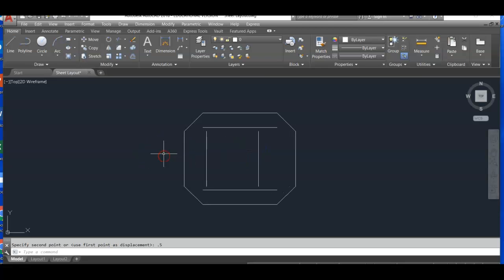0.5. Okay. Now we've got to clip these corners off, but take note, these corners aren't snapped together. That's one thing that's nice about this chamfer tool, it doesn't have to be. So we're going to go back to our same settings, except here the distance is not 1/4 inch, it's 1/8 inch. So I'm going to type 0.125, hit enter. The angle is the same, 45, so I'll hit enter again. Watch this, I'm going to click here, it joins that together and makes that chamfered corner. That's nice. Click here, and we're good to go there.